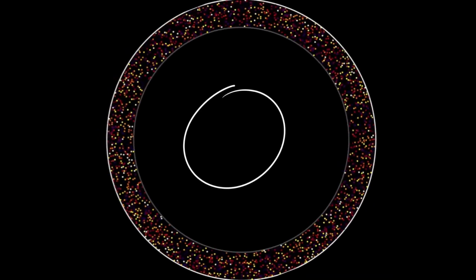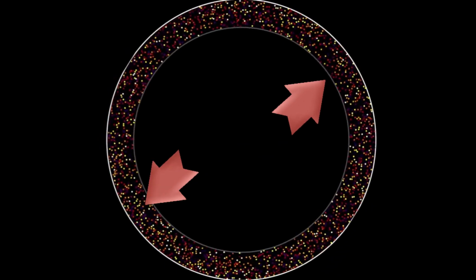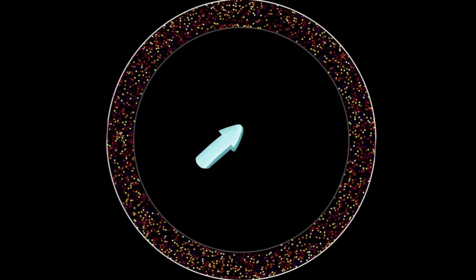Once the air is rotating, the pressure inside the tube is no longer the same everywhere. A radial pressure gradient forms. That means the pressure is higher near the outer wall and lower near the center. In simpler terms, the outer part of the flow gets pushed outward and compressed more strongly, while the center remains at lower pressure. As the vortex develops, two main flow regions appear.